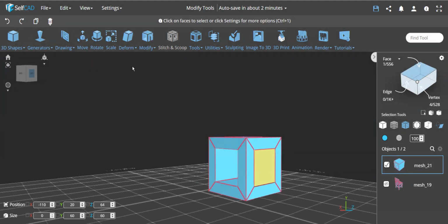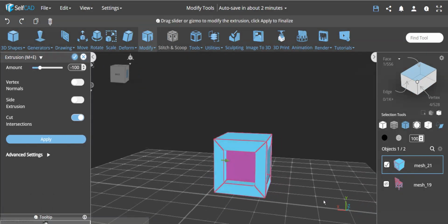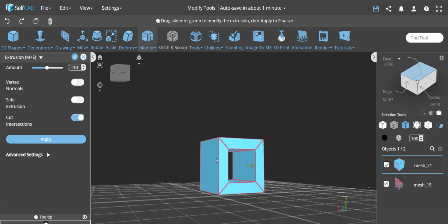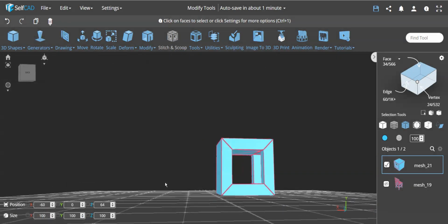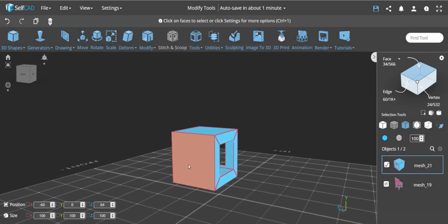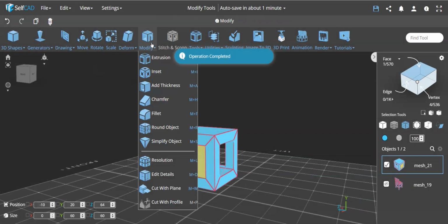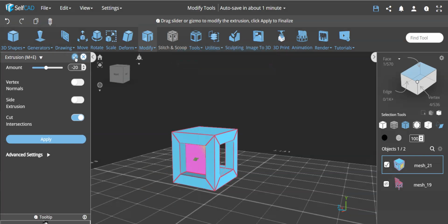So what I'll do here is I'm just going to extrude this by this amount, which I think I remember was 10 minus 10. No, actually it was 20. Let's see. Yeah, it was 20. Snap there, it hits 20. And now this cuts this one. And now I'm going to do the same thing over here. I'll select this one, I'll inset this, and then I'll extrude it by -20, and I did a cut.